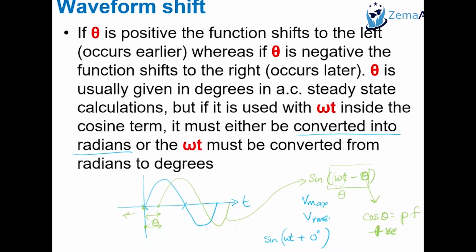And that's where the confusion is. But to speak technically correctly, the power factor is either lag or lead. It's not positive or negative. It's just our imagination that a lagging power factor is positive and a leading power factor is negative. So if you drop that convention from your mind and say, okay, power factor can never be positive or negative.